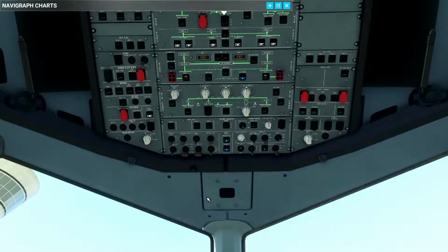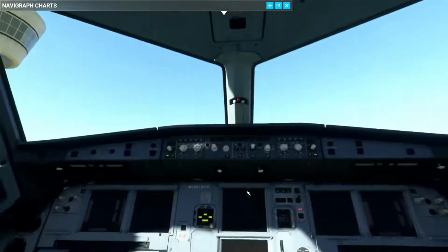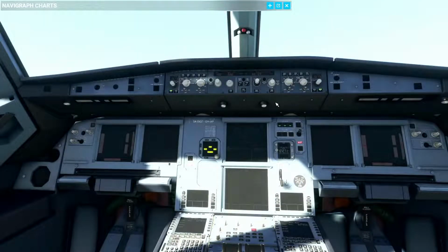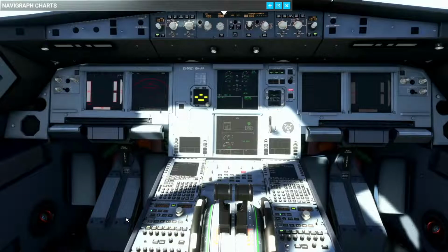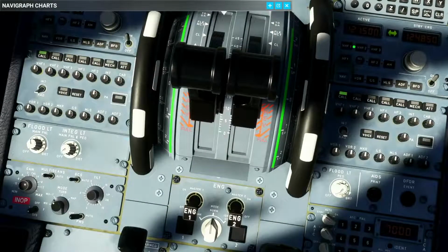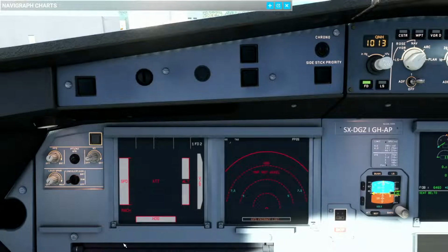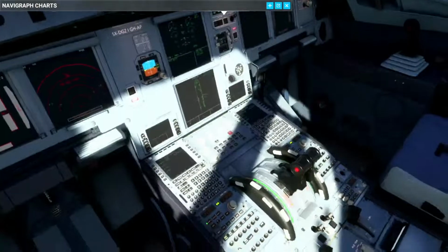Alright. First thing we do, we'll turn on the lights everywhere so we are sure that we will be able to see all the lights in the cockpit. Also here, increase the lighting intensity. This knob will control our primary flight display, the second one the navigation display. Also here you could set up brightness if necessary. For the ECAM we have 2 buttons here that we can turn to make the contrast stand out more. And then we still have the floodlights here and the backlight for our main panel. So that's the light setup.